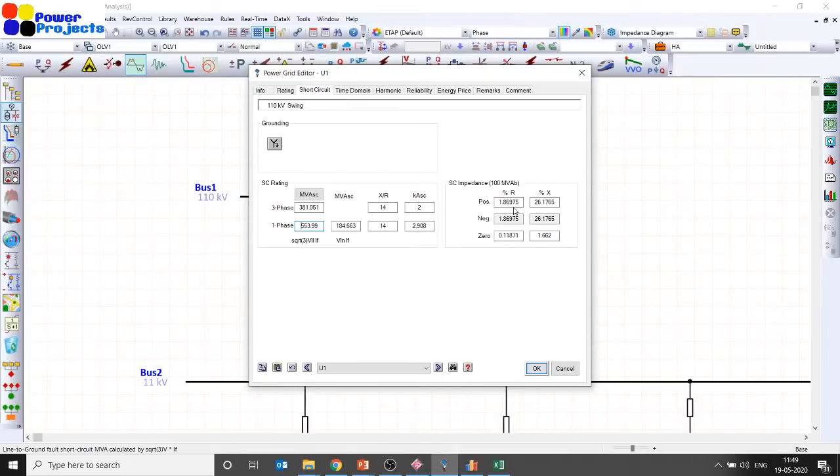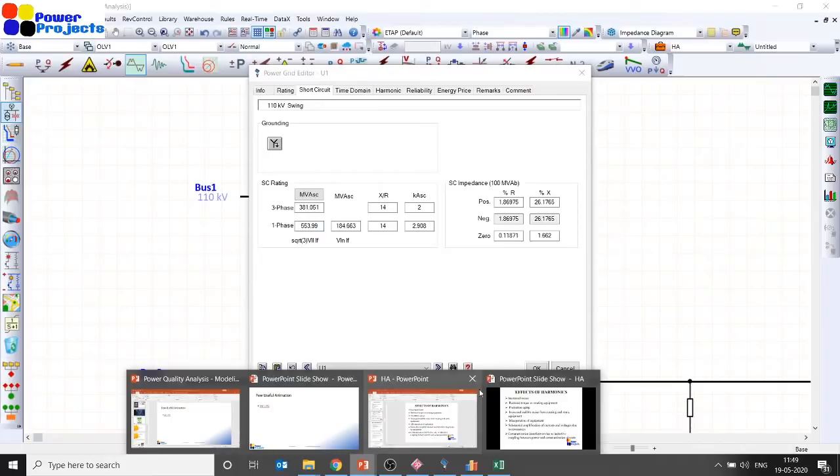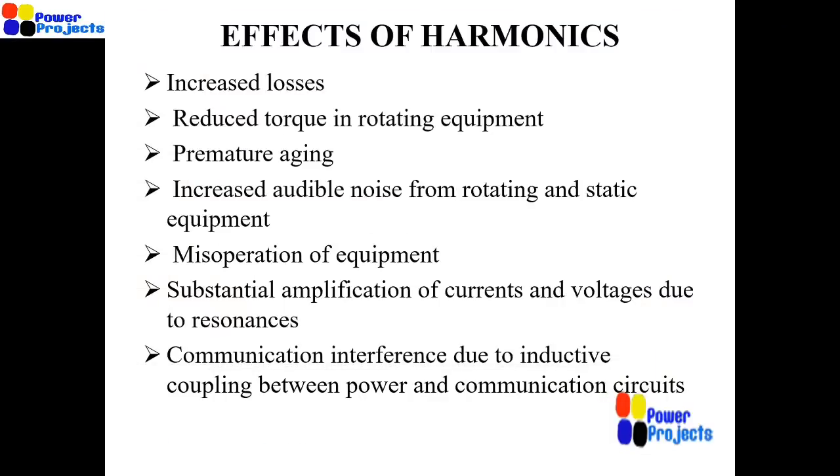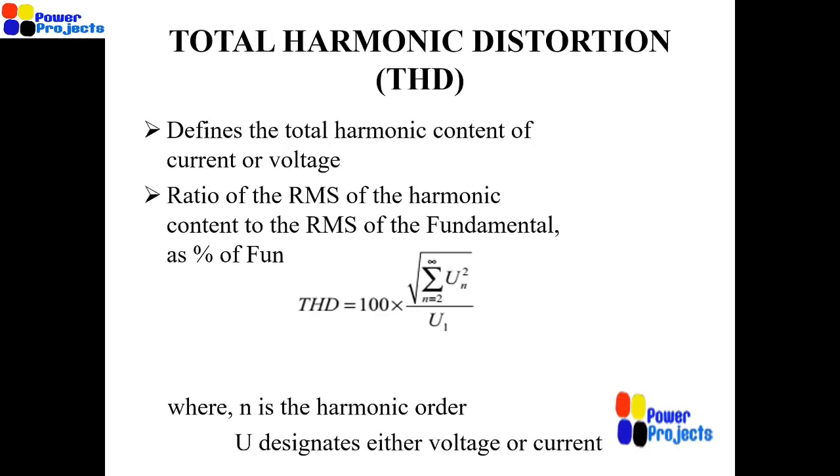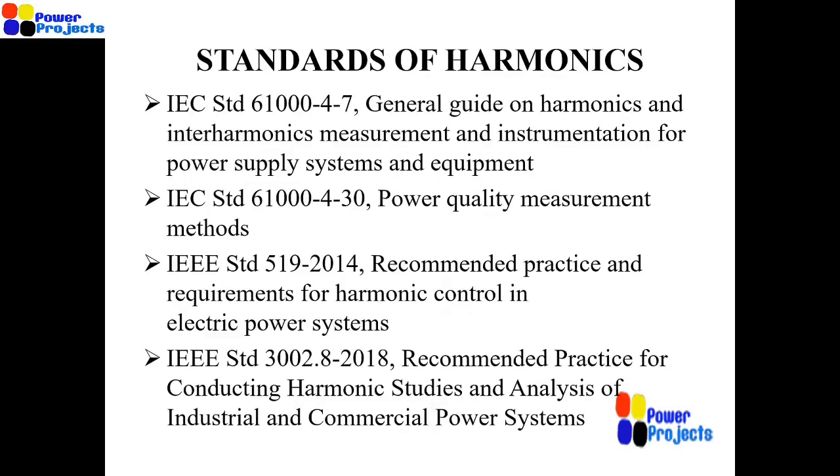Which IEC defines it? There is no direct relationship between cable sizing and harmonics; that's an indirect effect, and there is no IEC standard which talks about it. But there are IEC standards for harmonics. I think that's clear, that's to answer Gunasekaran's question. Somewhere she has made it. Yes, this is a standard of IEC and IEEE. That's clear. And the IEC standard for a cable is IEC 60502.